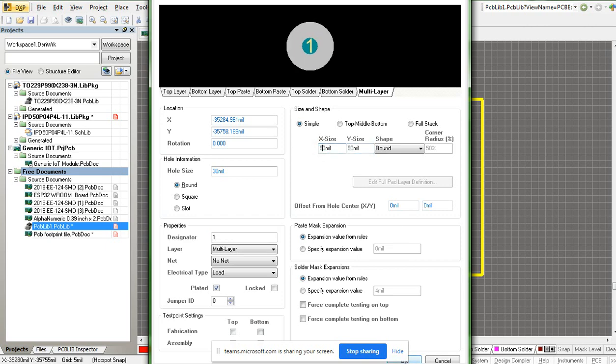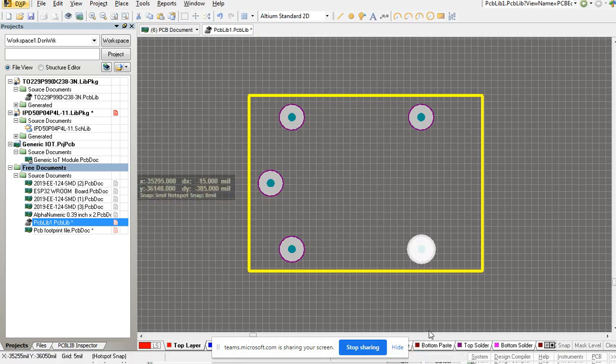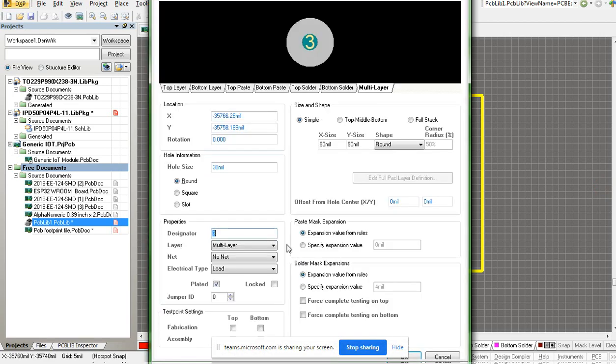Now I've still not named anything, because when you are going to use this footprint, this is going to be the common. So this one and this one are the coil sides. I can call this one, in the designator over here, instead of 3, coil negative. There is no harm. You can call it coil positive, coil negative. The relay will still work, because it's going to work as an electromagnet.